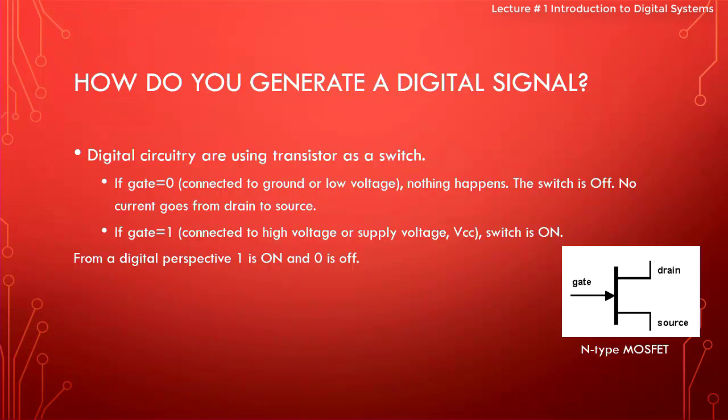Now what's the reason? Because our push buttons and switches are mechanical devices. So when we press a push button, this logic is supposed to go from 0 to 1, right? But what actually happens is it goes to 1, to the on, and then bounces back off because of the mechanical nature of the push button, and it fluctuates between 0 and 5 volts multiple times before it stabilizes.